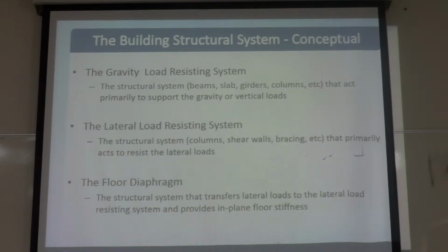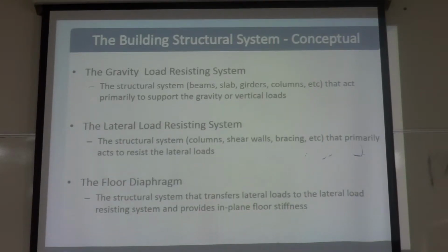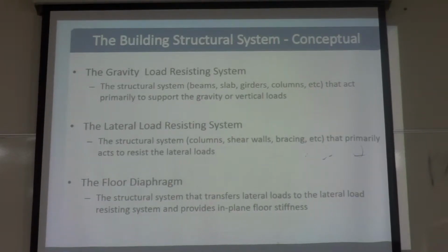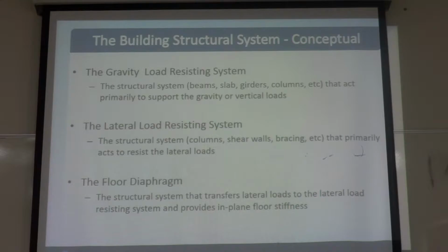And another system is the floor diaphragm. That one is to transfer the seismic loads. Normally, seismic loads develop in the floor due to the mass of the floor and the acceleration of the floor. So those inertial forces have to be transferred to the lateral load system by the floor diaphragm.